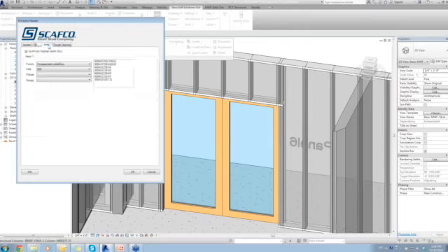And we have the priceless quick jam stud. Again, it knows I'm working with a 600, so it auto-filled that in for me. All I need to do is specify my desired flange. So I have my 238 or my 338 option, and then I have a couple of gauges I can narrow it down to. Specify this member. We jump to the rough openings tab.